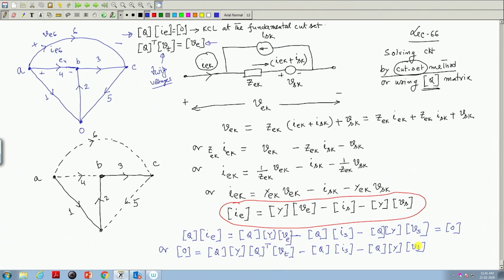See, here it is current, therefore, right hand side also dimensionally should be current. So, you can easily remember this is current, q matrix has got no dimension, only plus 1 minus 1 entry. So, it is in ampere, and V s is in volts, and volt pre-multiplied by admittance will give you also ampere, since q has got no dimensions. So, this is the thing.